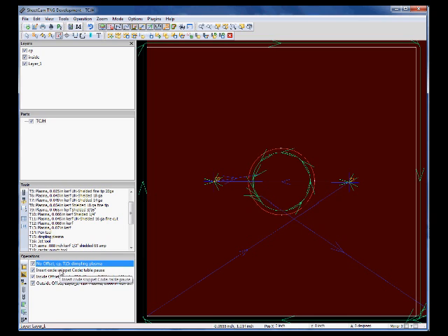You're doing your dimples, and then after the last dimple that you mark on your table, wherever it is, you put the code in there. It'll do all the dimples, then it will stop, you increase your amperage, and then hit cycle start, and it does all the rest of it. It'll go back to the first one, and it'll cut this part of it, and then it'll cut this part of it, and does the rest with all the rest of them. So anyway, that's what you need to do.